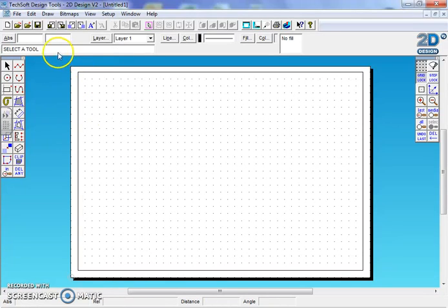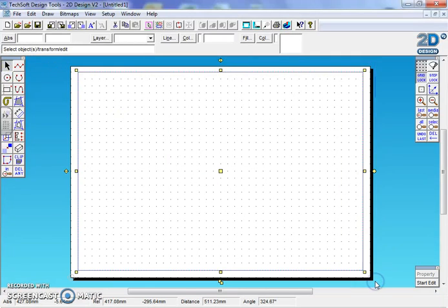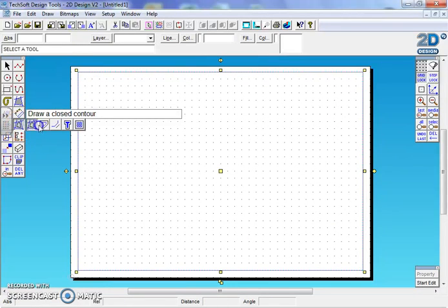Okay. Now, brilliant. Let's click on the select tool on the left hand side and click and drag all the way across your page from top left to bottom right to select the border that you've just drawn. And we're going to create another border that is 5mm away from that first one on the inside of this rectangle. Okay. To do that, we select it, go to the contour tool, click and hold down, and move to the second one along, which is contour selected objects.